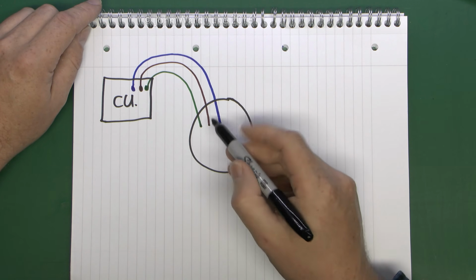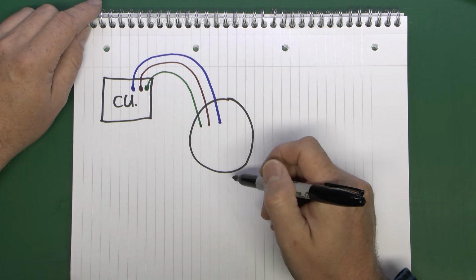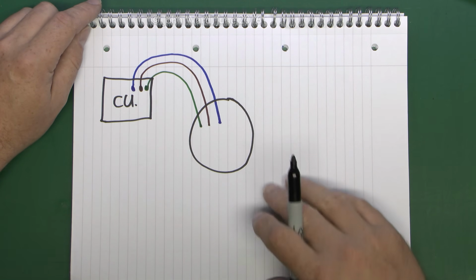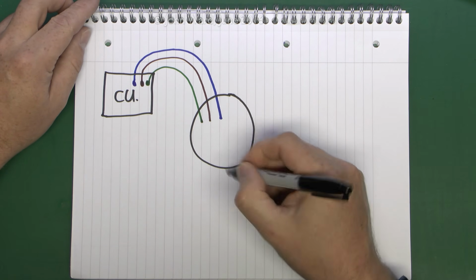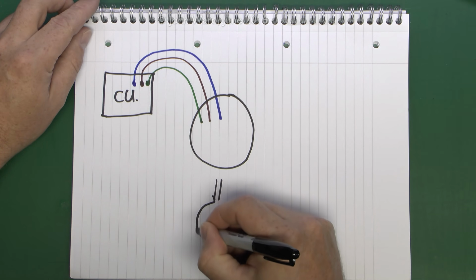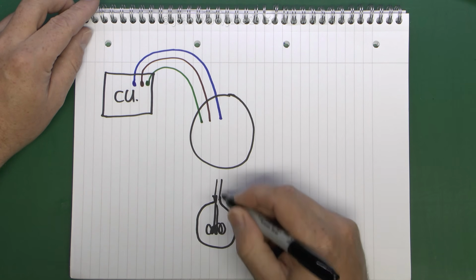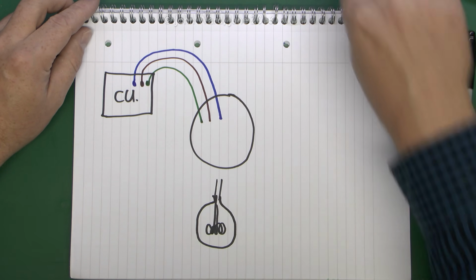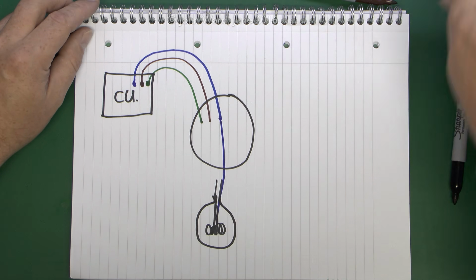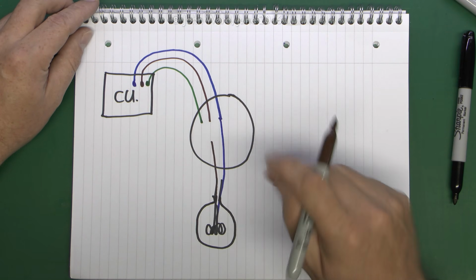Now, you could just connect the actual light bulb or lamp between the line and neutral there, and that would result in the thing being turned on permanently. But that's not what we want, so we need some other mechanism here. So we'll draw in the light bulb down here. This might be some old type with the coily filament inside, and it's going to have two wires coming out. We'll draw the neutral in, which goes straight into the filament, and the line, of course, will go onto the other side of that.